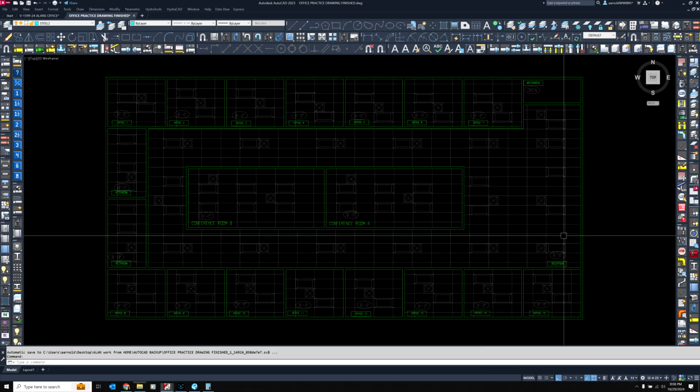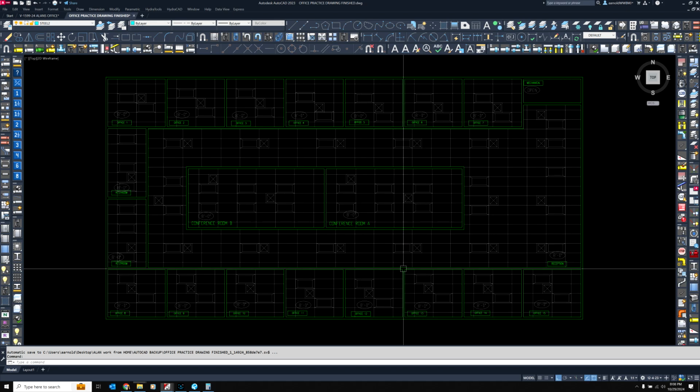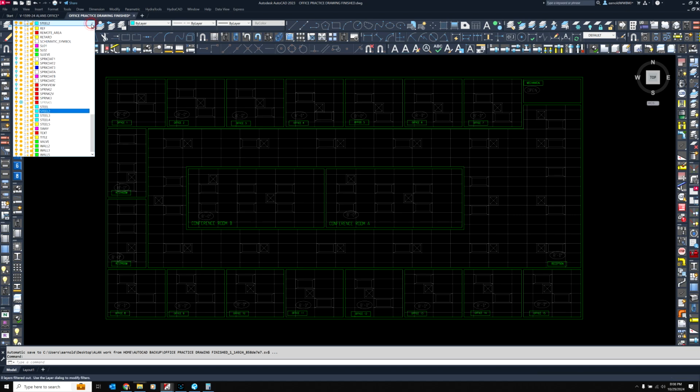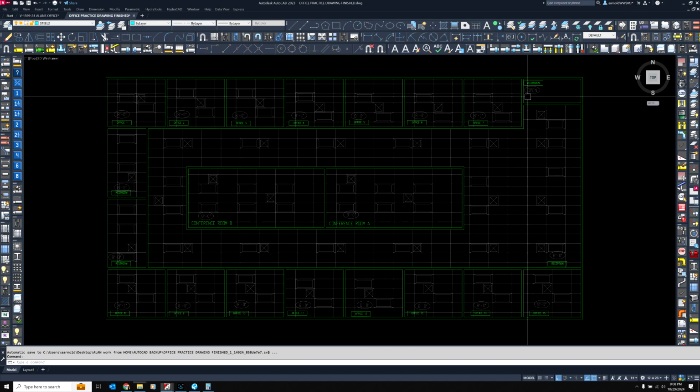We need to draw our first piece of steel and then space them out. And what we're going to do is make sure that here we pull down to the steel 2 layer. This will be our bar joist. If we had column lines to insert, that would be on steel layer here. Steel 2, you can see it's the cyan color. Your line type actually has a dash and a dot. We want that. And now we're simply going to draw a line from top to bottom.